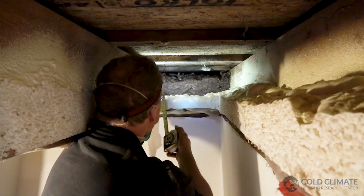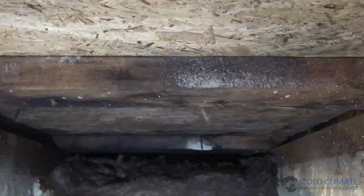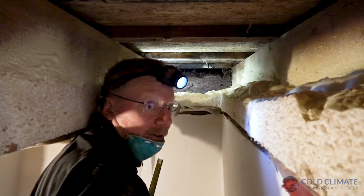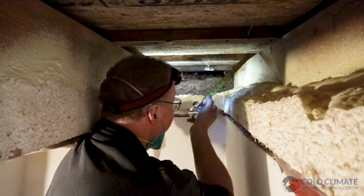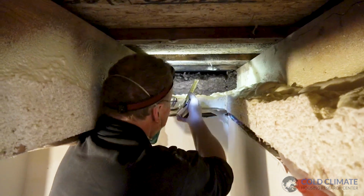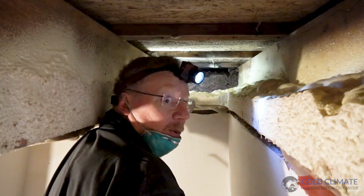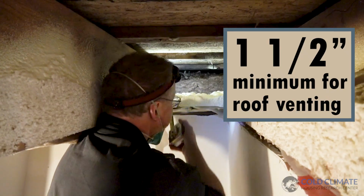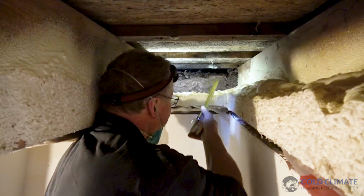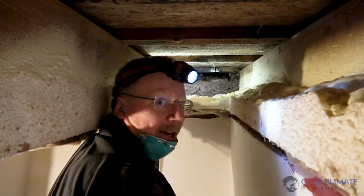And we can see here from the dry rot fungus that has started on several of these purlins and the dark staining that this has been going on for a while. So the other thing that needs to happen, in addition to air sealing all the leaks in the common wall, is the builders need to make sure that at least a 1.5 inch airspace continuous from soffit to ridge exists. So if any moisture does get into this roof system in the winter, you've got a proper drying path.